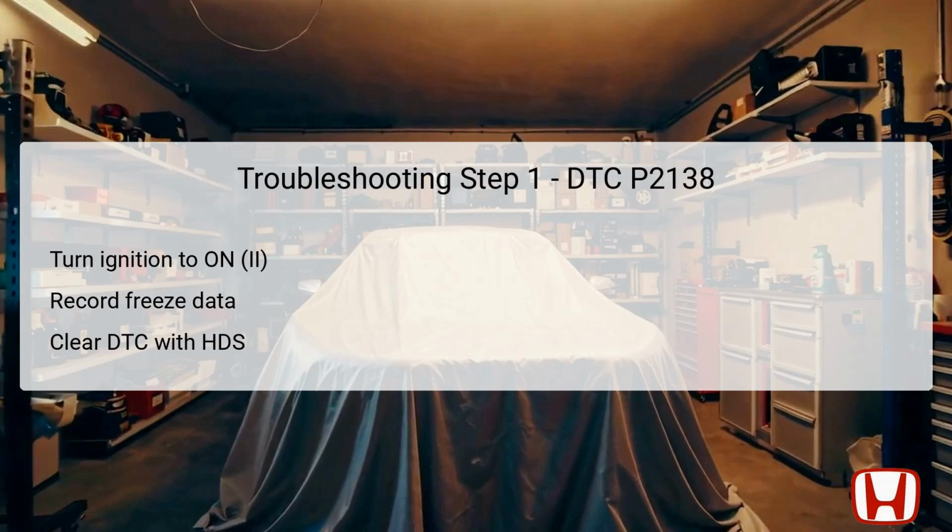Next, it is essential to clear the DTC using the Honda Diagnostic System, HDS. Clearing the code will reset the system, allowing for future diagnostics and observation of any recurring issues without previous error interference. Overall, these initial steps prepare the technician for a thorough examination of the issue.